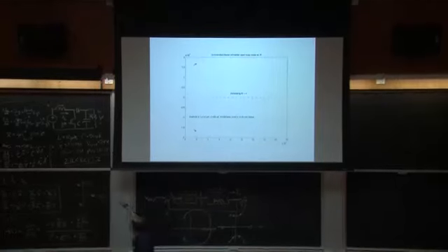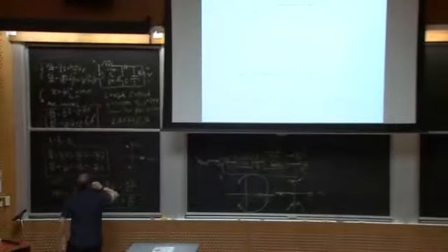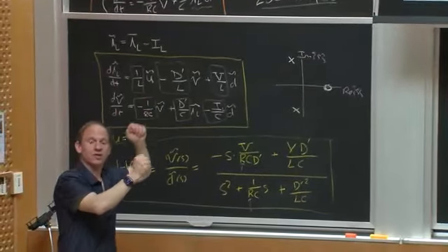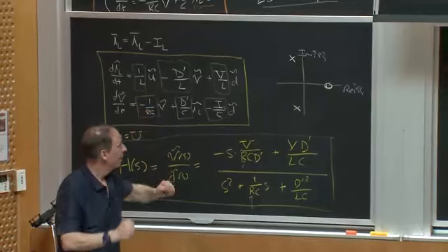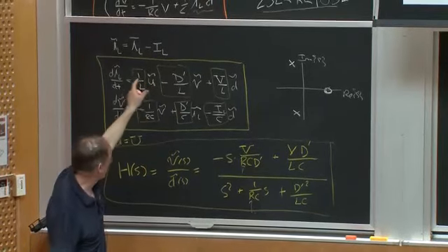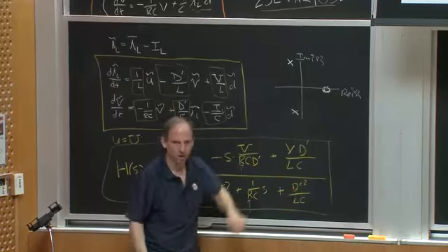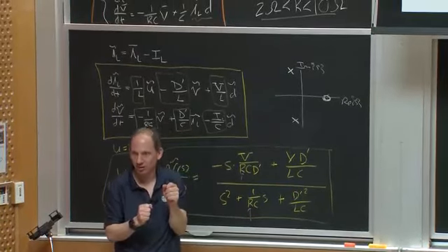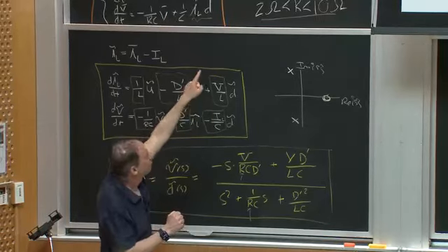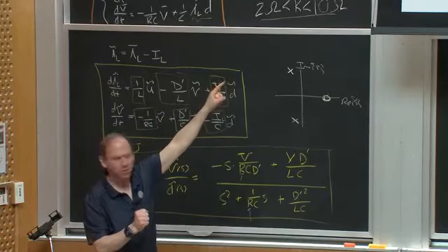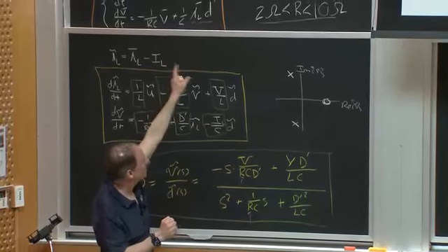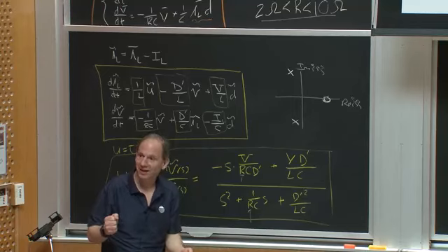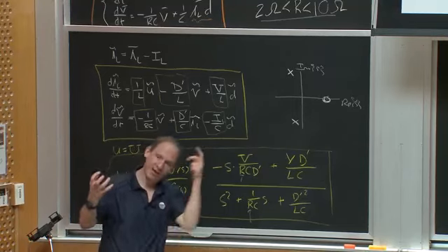Well, if you think about back to the original converter, what's happening? Essentially, L and C are oscillating. Okay, they slosh energy back and forth dynamically. Not just directly, because they're not directly connected, but modulated through the duty ratio. They're still trading energy back and forth. And that's the source of oscillation. That's why it's second order and can be underdamped. Okay? The resistor damps that. Right? So it's some funny modulated version of the LC oscillation with a parallel resistor. So basically it's like a parallel resonant tank, and the resistor is what's damping that thing.